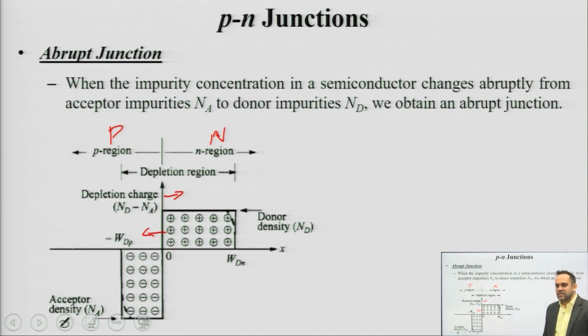This kind of assumption or arrangement greatly helps in easing the analysis of a p-n junction. All the electrostatics associated with the p-n junction become quite easy and simple when you assume that you are working around an abrupt junction. It is easier to write the equations, and it is easier to identify boundaries and limits for the mathematical analysis.